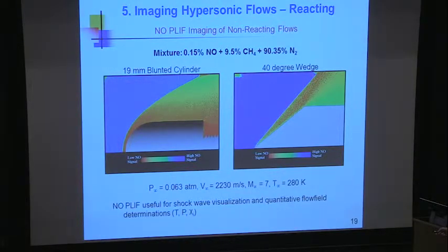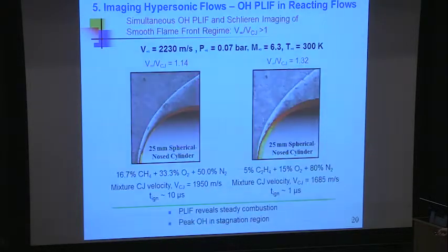This is how people calibrate these tunnels. They measure this angle and say, I know this angle, I measure this angle, and I know gamma. I've just determined the Mach number better than I can calculate it. That's a common trick. So we could do this. This would be like Mach 7 in this case, and we could have a free stream temperature of about 280 that simulates maybe atmospheric air.